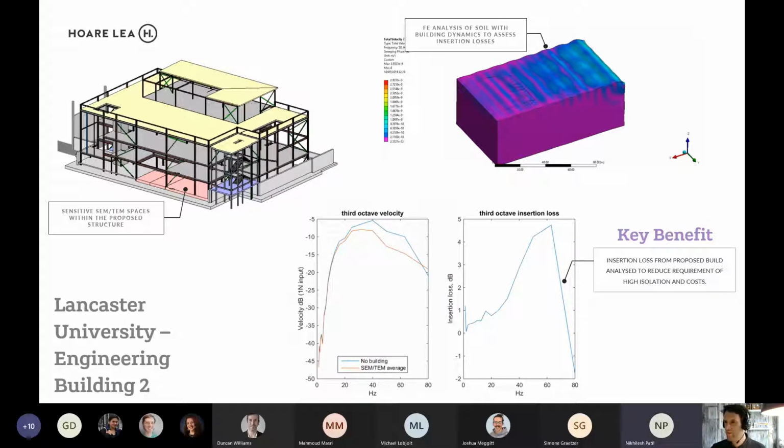Yeah. Okay. So when I say Monte Carlo in a consultancy setting, what we do is we parameterize different parameters of the structural form. That could mean changing the thickness or the Young's modulus and different dynamic properties of the structure itself to see what the effect is. So you have a number of inputs with a number of different parameters, and through modeling each of these combinations of parameters, we try to find an optimum solution.